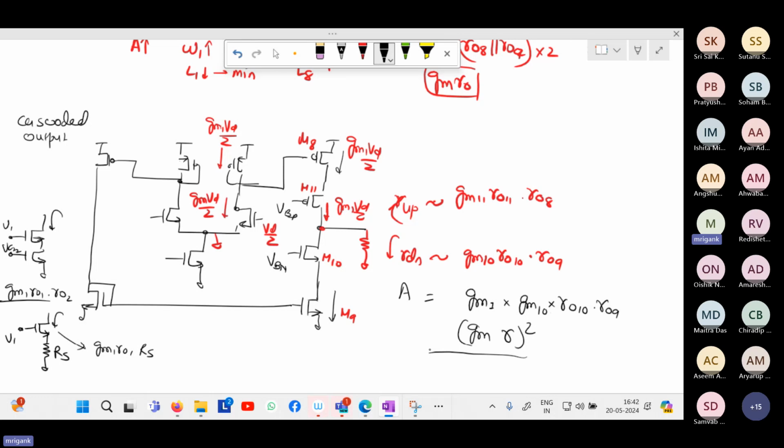So now in this case, what is the pole scenario? The first stage anyway, still these are low impedance nodes. We don't get a significant pole from here. These are all going to be at very high frequency, because these are low impedance nodes. 1 upon RC constant is high frequency. What about the output node? What has happened to this pole?